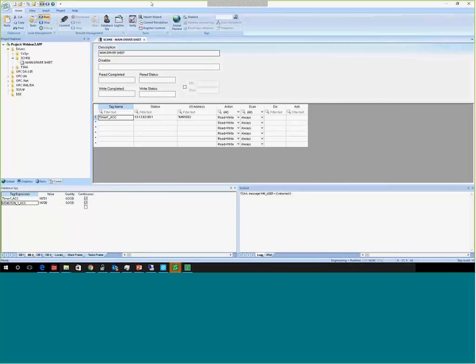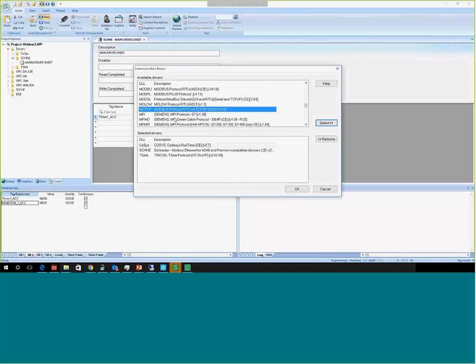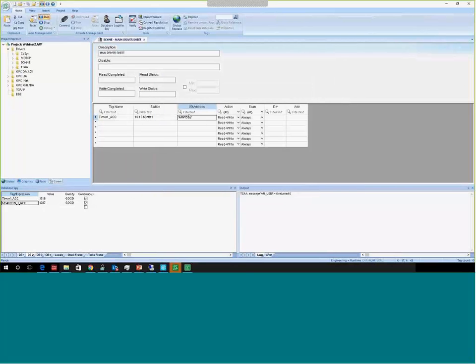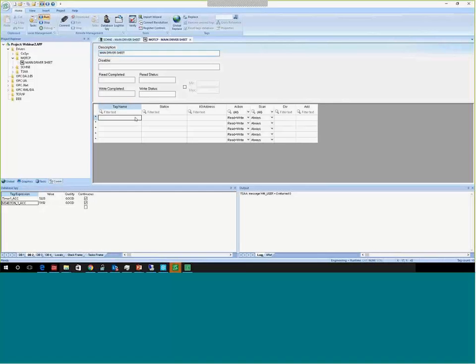And talking about different ways, since this is a Schneider PLC, it speaks Modbus. And the relationship between the %M and the Concept address is very simple. So let me add here the Modbus driver, Modbus Ethernet driver. I'm going to go to the same PLC. So MOTCP, I'm going to put here. Going to be my timer 1 ACC using the MOTCP driver.